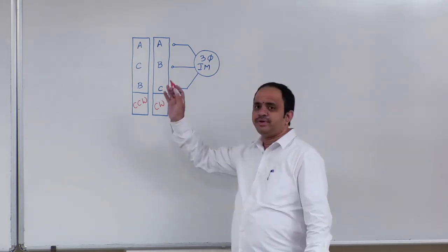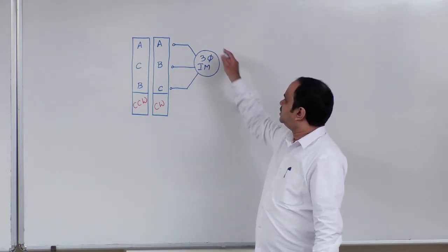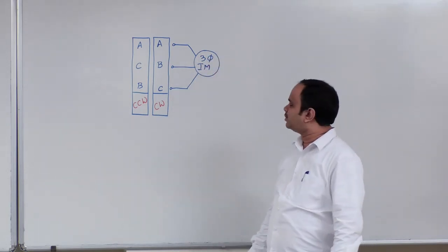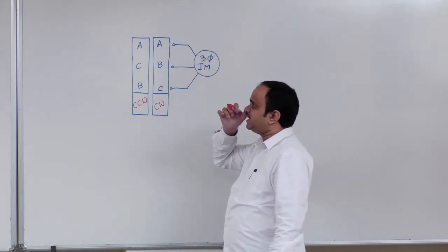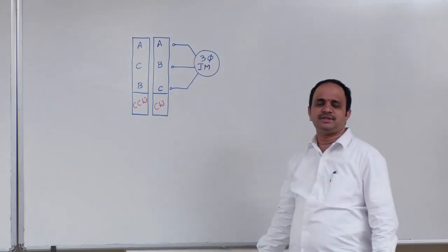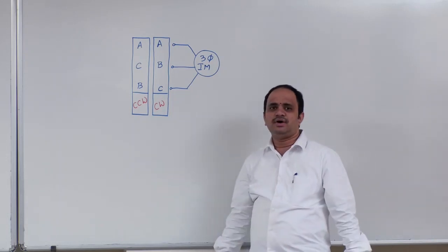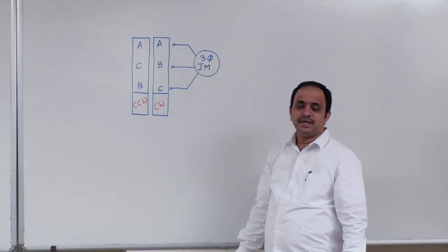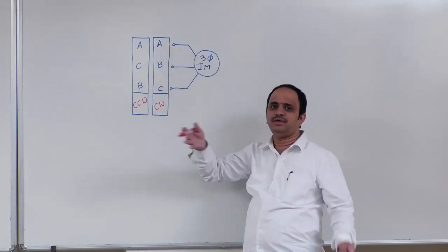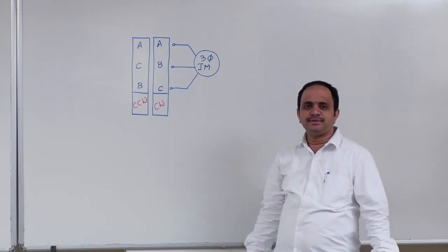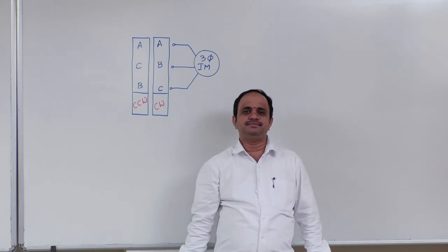Now, before moving further, let us have a basic working principle statement. For example, the stator of a three-phase induction motor generally has a distributed three-phase winding. If the three-phase distributed stator winding of this induction machine is supplied from a three-phase balanced source, for example ABC sequence, then what will happen? A rotating magnetic field will be produced in the air gap.